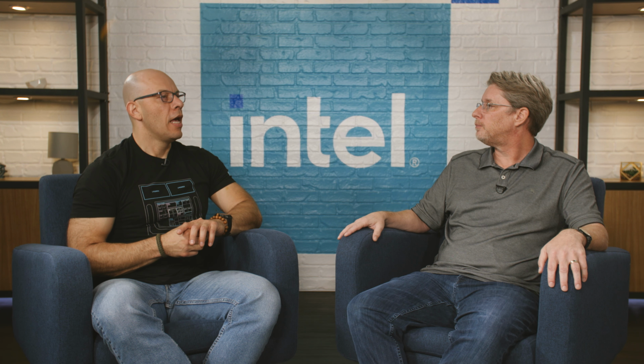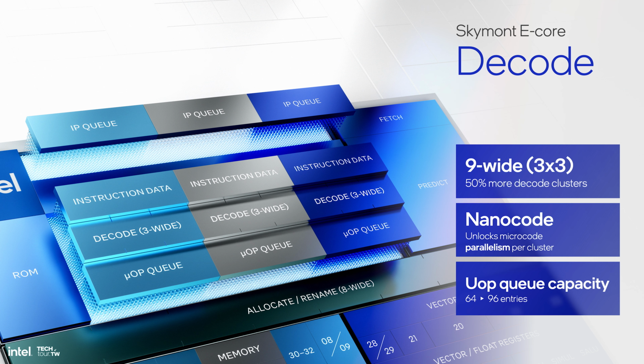On the P-core side, we have a UOP cache, something that holds decoded instructions. On the E-core, we've taken a slightly different approach. Instead of having to pay for that cache, we have what we call clustered decode in the front end. So it's just another way of solving the x86 decode challenge, which we believe we've solved. It's variable length, so different microarchitectures.